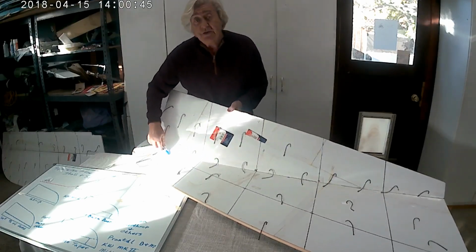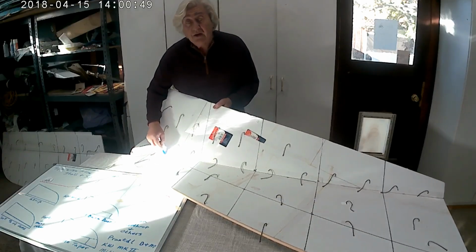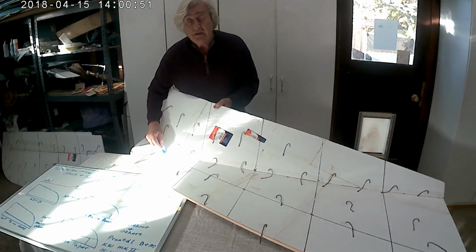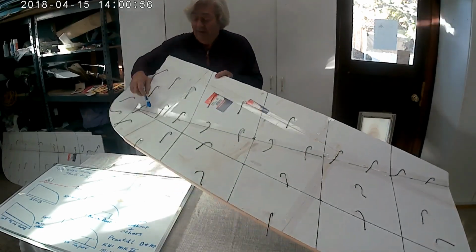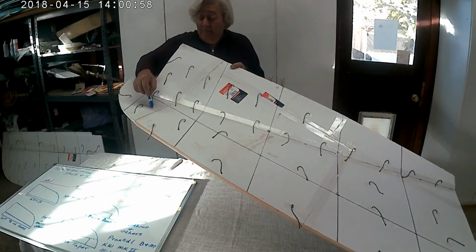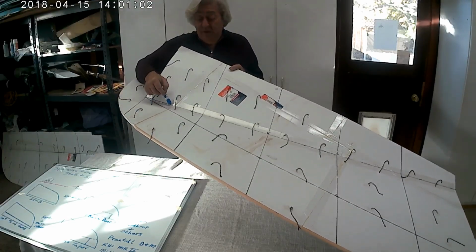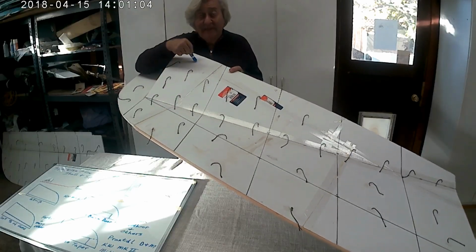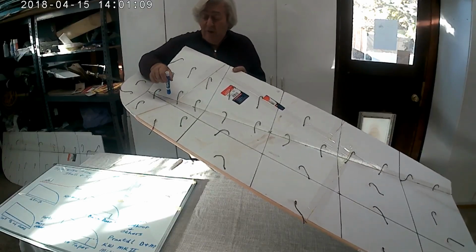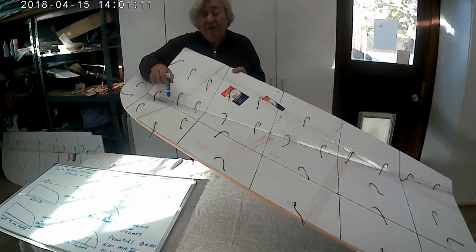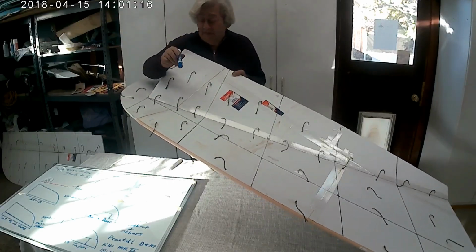Oh, look where the hinge line is. There's our answer. This hinge line here is at 30% of chord from the leading edge. This spot right here on the wing is the maximum speed that the airflow gets to going over this airfoil. From this point aft, it's decelerating. From this point to here, it's accelerating. So, the maximum thickness point of the airfoil is where there's the maximum velocity and hence the maximum momentum.